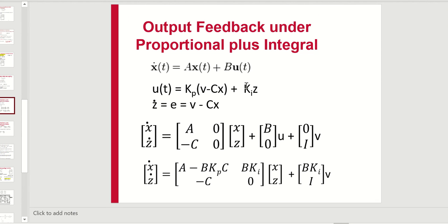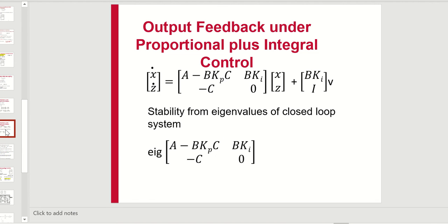So these now could be the state space equations of our classical multivariable PI controllers. You've got x dot is Ax plus Bu, z dot is v minus Cx, and then these would form the closed loop state space equations, just as we've achieved closed loop state space equations for other state space representations. This equally well works for multivariable. That's the beauty of state space. We can extend it from single input to single output, and it's exactly the same, which is highly advantageous.